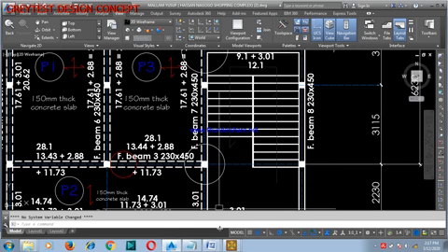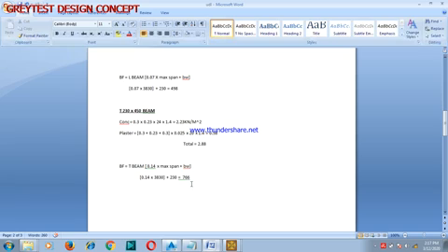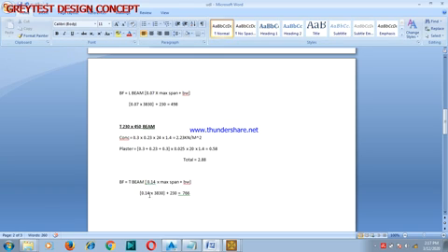Beam 3 is a T beam. Okay, now go back here. For our T beam, it is 0.14 times the maximum span, but the span is actually equal, so the maximum is definitely going to be 3830. Now, like I said earlier on, the span might vary. You may have different sizes of span, they may not be the same. So in that case, you pick the highest. Okay, 0.14 times the maximum span plus your breadth of flange, which is 230.